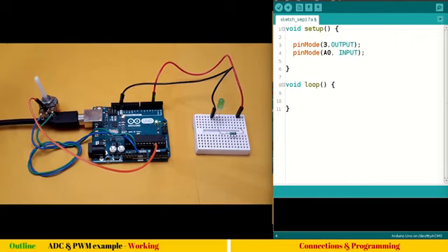And also we want to know how this analog voltage read from the analogRead function looks. So let's view the output voltage in the serial monitor. For that, you know what to do. Serial.begin, default baud rate, bits per second, 9600.